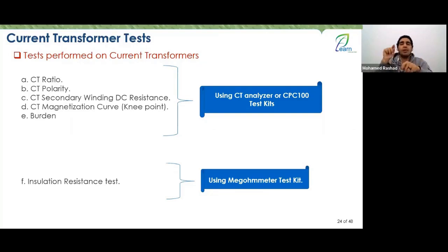The other thing we mentioned is the idea of how the current transforms with an angle, and we talked about the topic or the characteristic of the primary and secondary polarity. We said when they are drawn opposite, what does it mean? The primary is drawn on one side and the secondary is drawn on the other side. This means it is additive polarity.